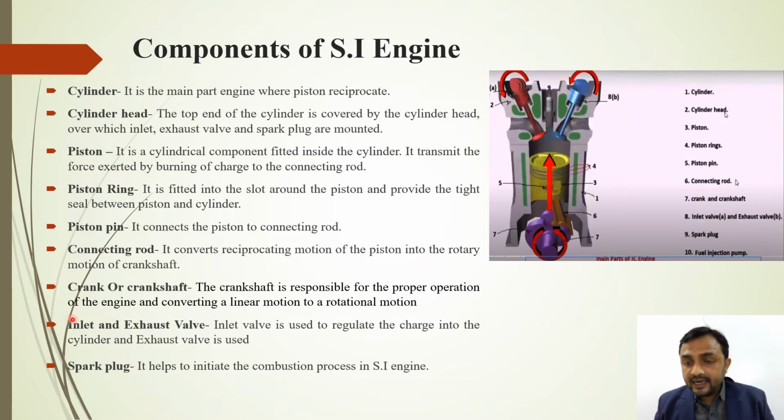Next one is your inlet and exhaust valve. The inlet and exhaust valves are used to regulate the charge into the cylinder and out of the cylinder. You can see them here at number 8: this is your inlet valve, 8A, and this is your exhaust valve. They regulate the charge. What do we mean by charge? This is the air-fuel mixture.